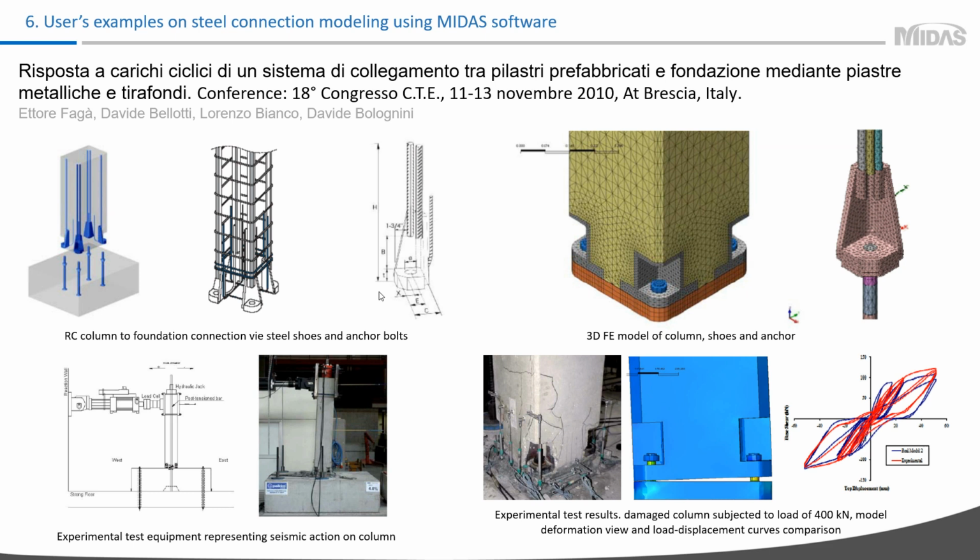In this investigation, authors considered different finite element models of this connection and did a comparison with experimental test. You can see a 3D solid model where all parts are made of solid finite elements, and contact interaction between parts was performed using interface elements. For the concrete, a total strain crack model was also used. On this slide, you may see a general view of the experimental test, some results of experiment and analysis, and a comparison.